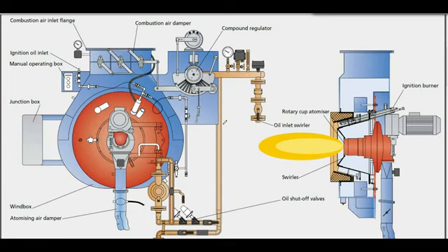And after that, the main fuel oil goes down to the shut-off valves. There are two automatic shut-off valves and one manual shut-off valve, and there is a recirc line. After that, we have a flow meter here, and there is a flow meter bypass which is kept always shut. After the flow meter, it enters the burner through the hinge of the door. This has to be noted.